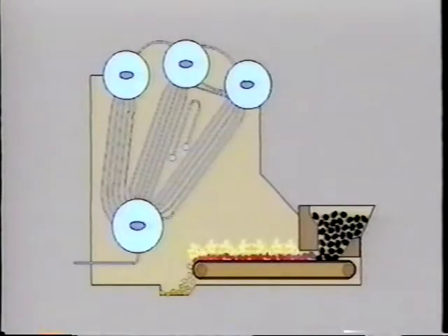Coal-fired boilers use mechanical feeders or stokers to feed coal to the burner at a consistent rate. For example, in a chain grate stoker, coal is fed through the hopper and regulated before passing under the ignition arch. The coal continues on a conveyor which carries the ignited coal slowly under the heating surface. Ash, slag, and unburned parts or clinkers are discharged at the other side of the conveyor.